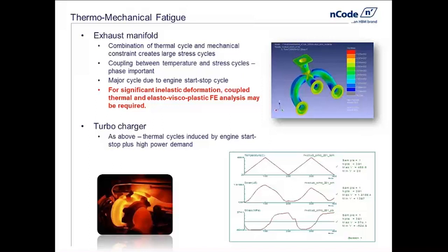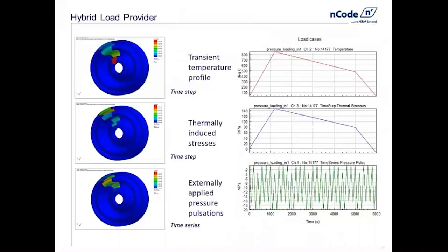So basically there are two separate styles of problems, and we see both in Powertrain. We're going to look at some of the enablers inside DesignLife to try to handle this. The first is the load provider. A load provider in DesignLife is a way that we take various finite element results and sequence them into a stress or strain temperature history that represents our part.